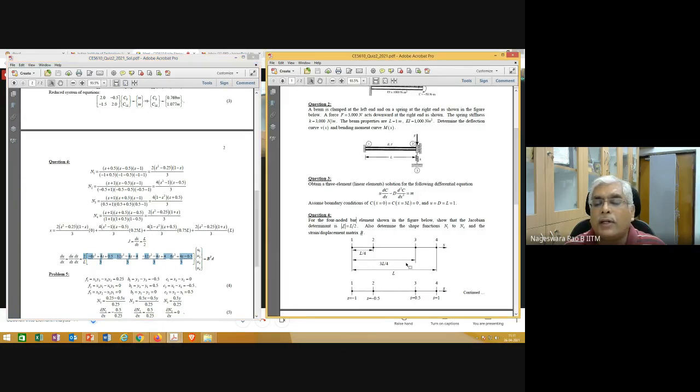The idea of testing you in this is that you can easily derive the shape functions as well as these kinds of relations for any custom element, depending on your requirement or for research purposes, if you want to use a higher order element. Also please note that in all commercial software, you may have only up to quadratic elements.